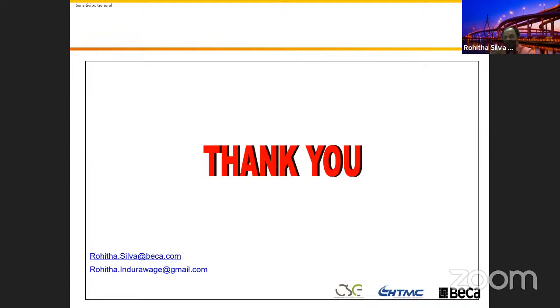And the girder spacing, sometimes they put more than that, but I think definitely those bridges they can design with more diaphragms provided along the length of the girder. Like I explained on that last slide, for a 25-meter span, we increased from 4 diaphragms in the span to 7. That gives us better behavior here.